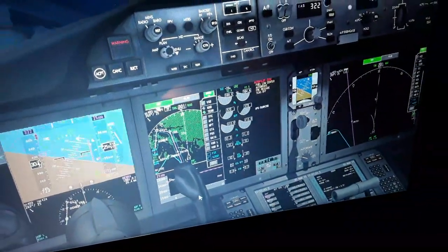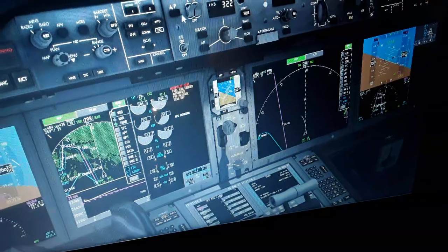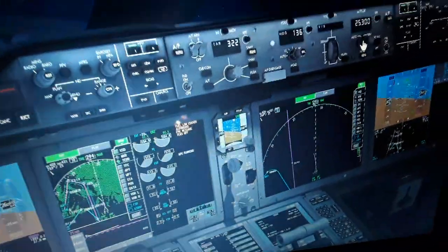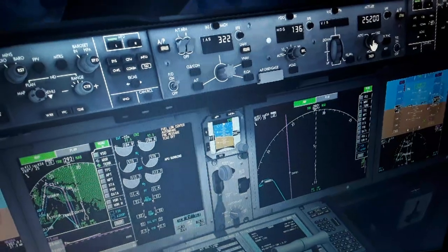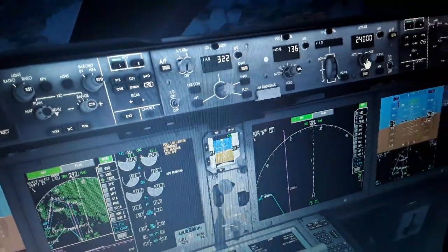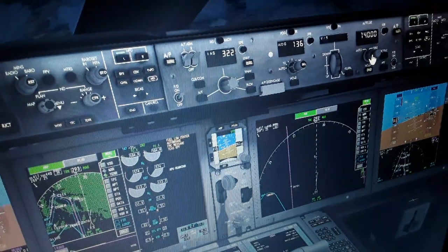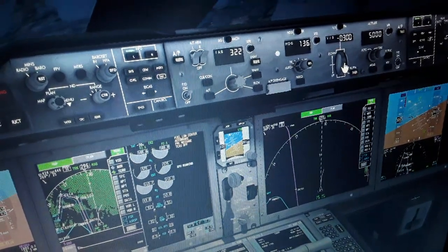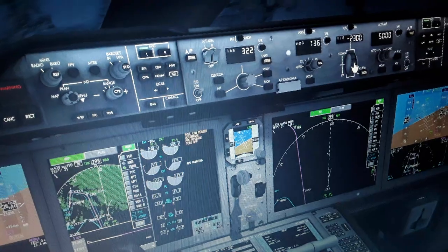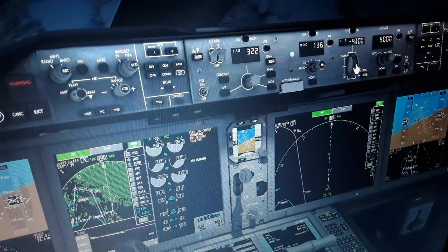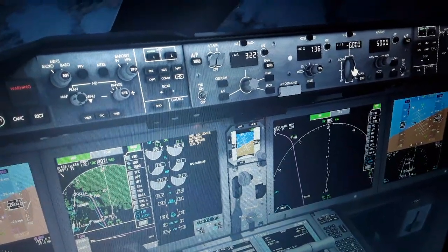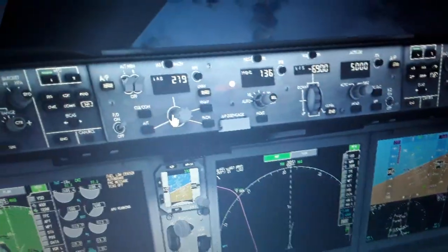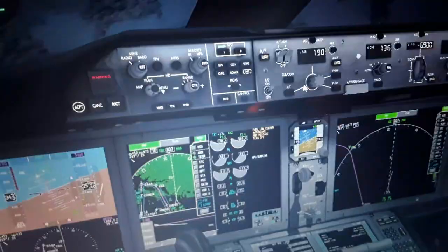We need to descend in a while, so we autopilot again. Use the LNAV. Also the descent over here, I'm gonna start descending. Vertical speed. Increase the vertical speed here. And decrease the airspeed. So this is following the autopilot mode, as you can see.